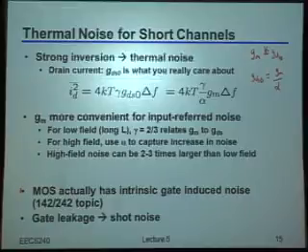Well, it turns out we're lying ever so slightly, because what really happens is that, even the instant that you put a new voltage signal on the gate, it takes some time for the electrons or holes inside of the MOSFET to actually show up in the channel. Because of that time delay, there's effectively a resistance in series with that gate.